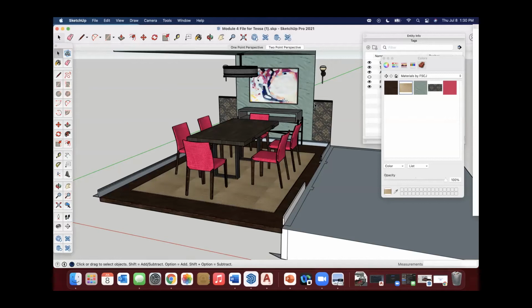In this video, we are going to learn how to work with scaling your materials. That means how to determine the scale of materials that we apply in renderings, how to change the scale of materials in the materials library, how to apply scaled materials to a surface, and then how to check that materials are scaled correctly once applied.